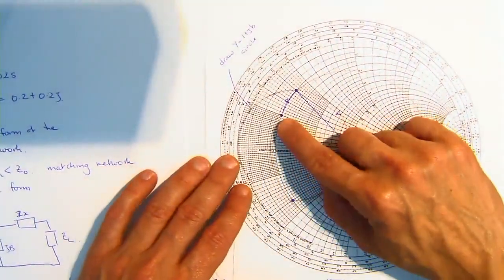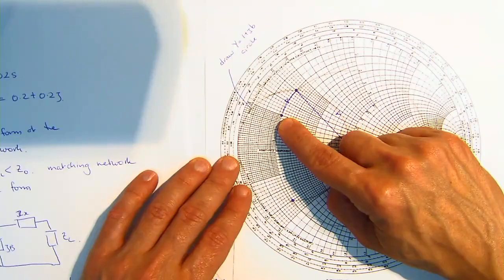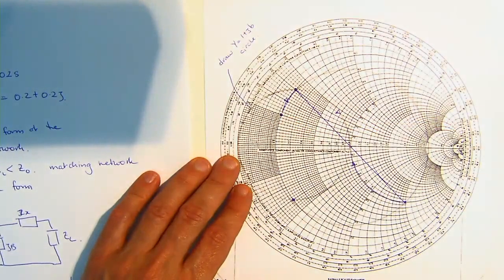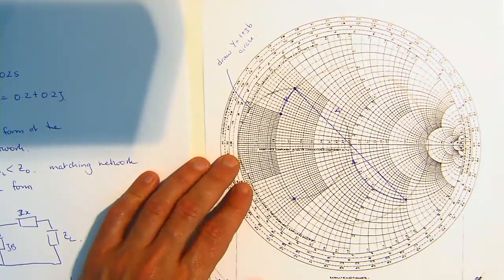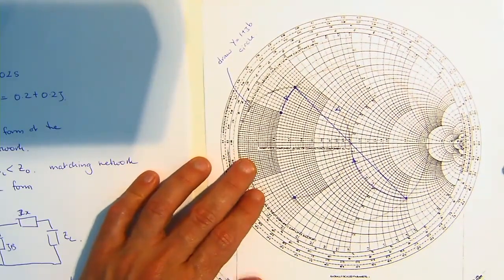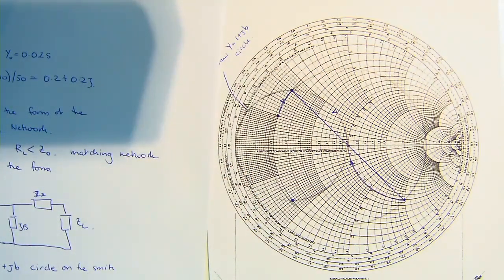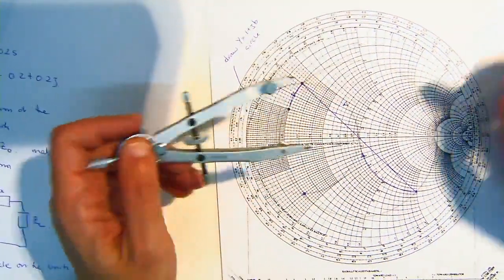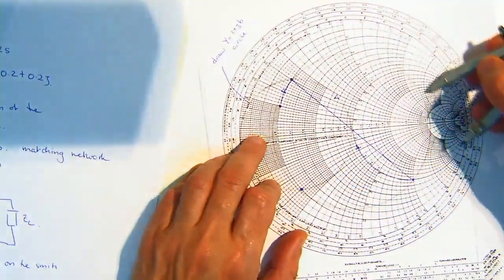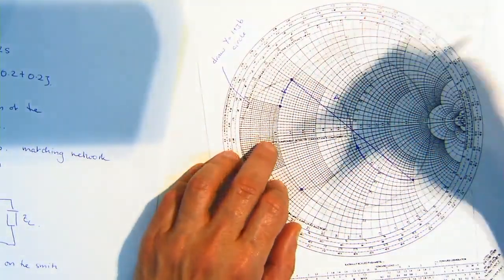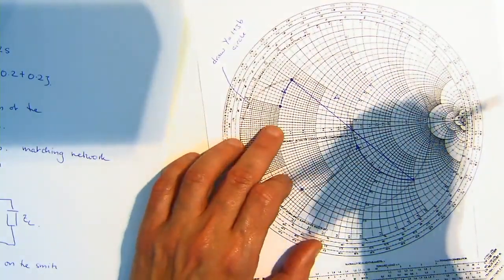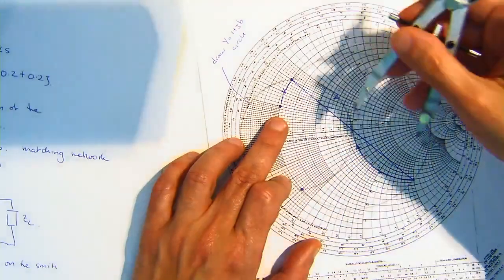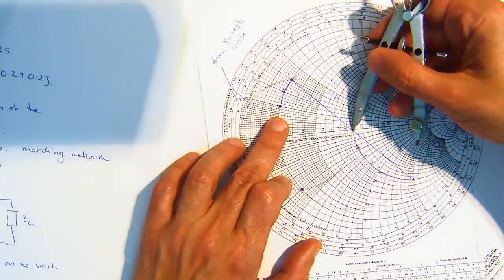Smith chart. Okay, so we know ZL is here, and we want to add some reactive component to it. Now, in order to work out what the reactive component is going to be, what I suggest is you also work out, because you don't really know what reactive component you should add, right? So now you're going to ask me, what are the potential reactive components that I can add in order to allow me to add a shunt so that I can get to the origin?